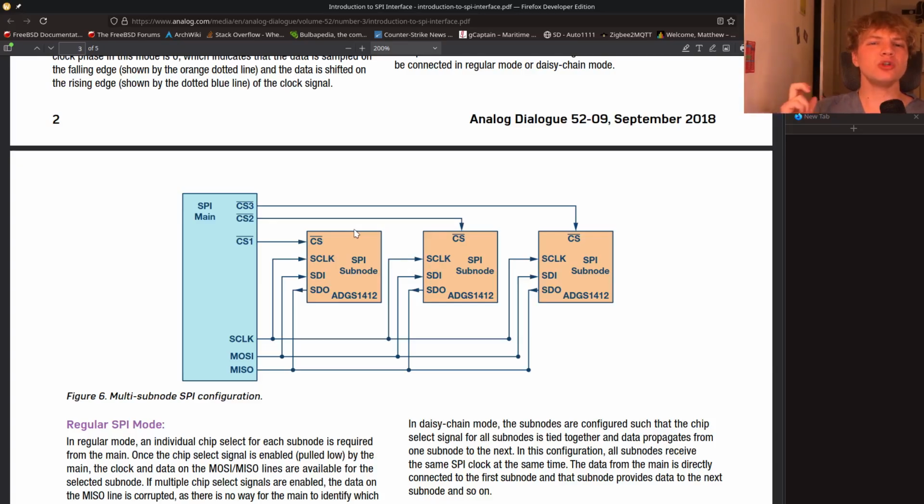So, why would you use SPI then? Well, if you can manage that trade-off, it's actually pretty quick, especially compared to I2C. And it's got flexibility that you can build your own messaging layer on top of it in such a way that I2C generally doesn't have. Now this can be a benefit or a drawback to you. If you want to build your own messaging layer or you have a need to build it, then the flexibility afforded by SPI is really good. If you don't really care to build your own messaging layer, I2C already comes with a pretty much pre-built framework of reading and writing to registers. So we'll jump into that next.